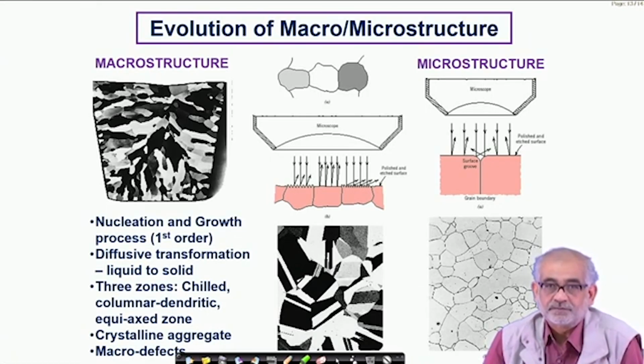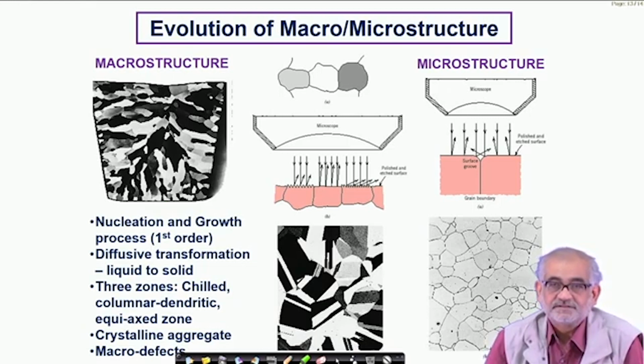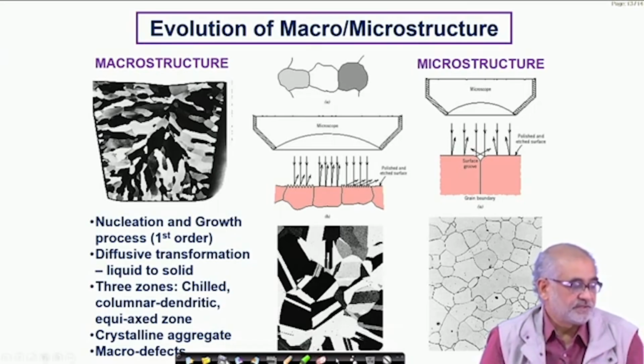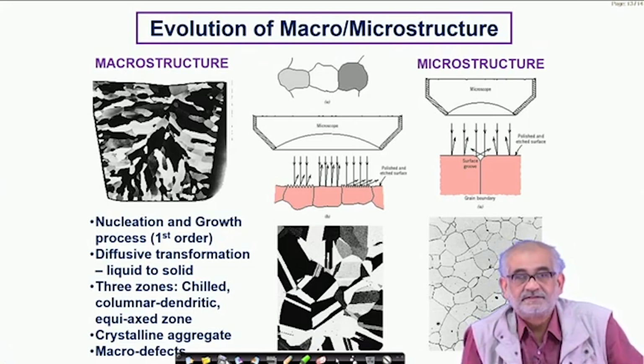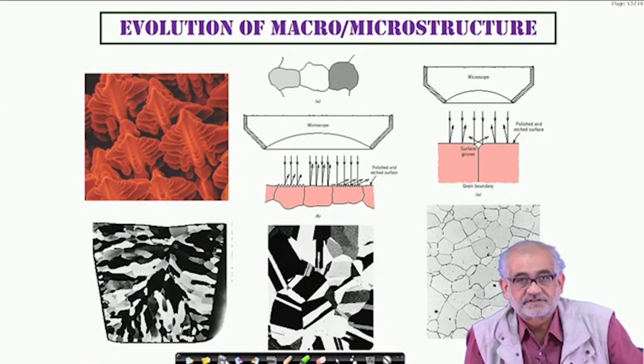So again, microstructure is a composite body of knowledge which talks about the phase, shape, size, identity, orientation, and volume fraction of the phase or the phases that are present in a given system, and the total aggregate, the manifestation, determines both structural and functional properties that this solid would show. We'll of course learn more about microstructure as we go down this course, and would be in a position to realize how important it is to understand the details of the microstructure.